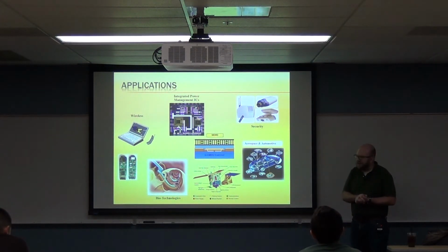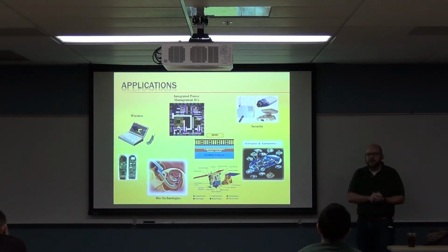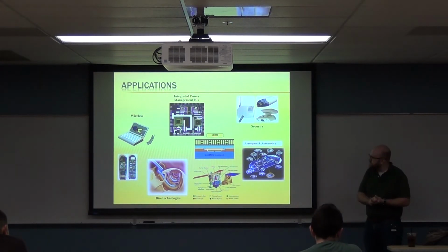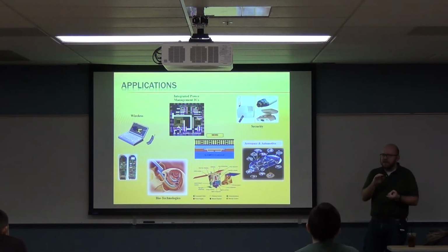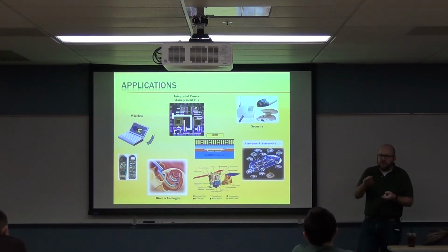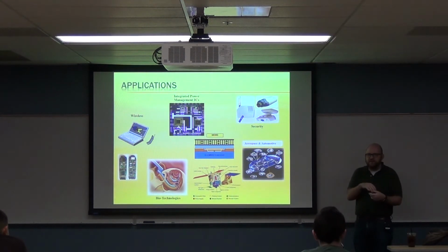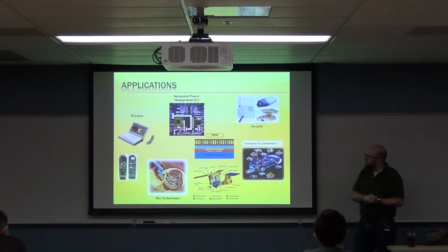So when I built a self-flying blimp for my capstone, don't worry, it didn't actually self-fly. The bar isn't that high. We put 5 or 6 accelerometers on it to do the dead reckoning. We put 2 or 3 gyros on it, and a lot of this was the controls that came up with this. We spent a lot of time trying to figure out how the circuits worked, because in those days you couldn't buy a digital sensor. What you got was an analog sensor. You were responsible for building the analog amplification pipeline with all the control gain, and then reading it into an ADC, and then figuring out what it actually meant. These days, they'll give you ADCs you can read over SPI, and it's a beautiful, beautiful thing. You just have to think a lot less.